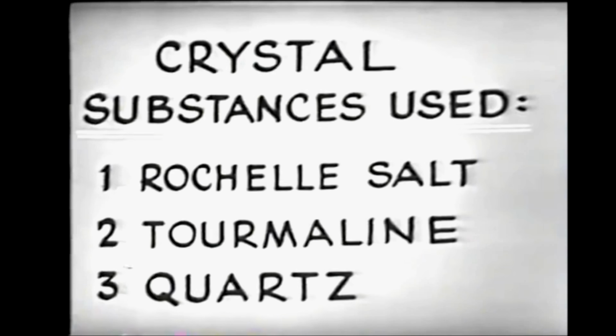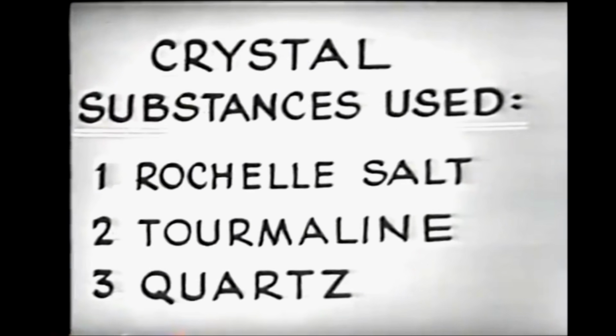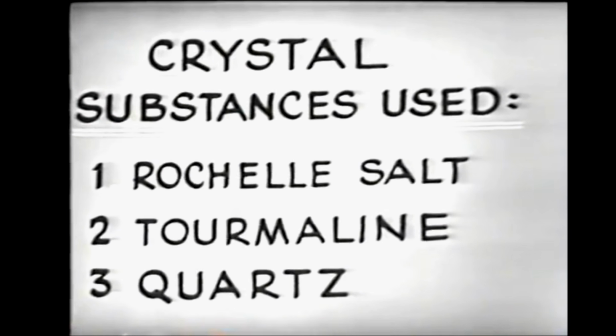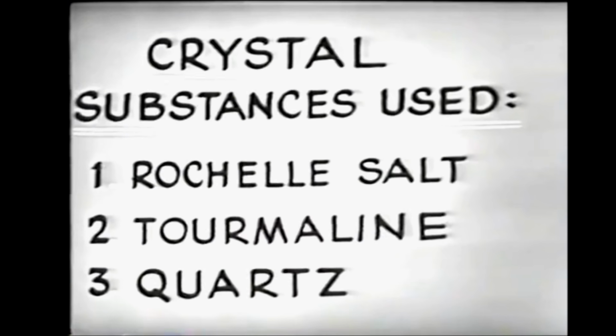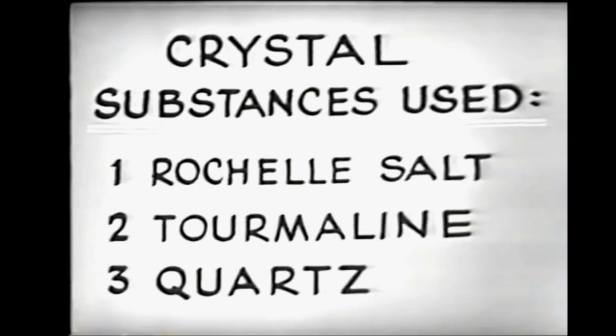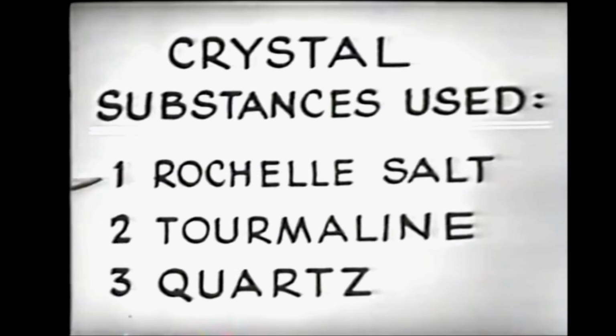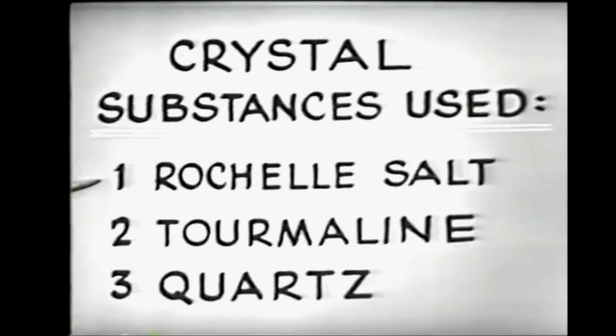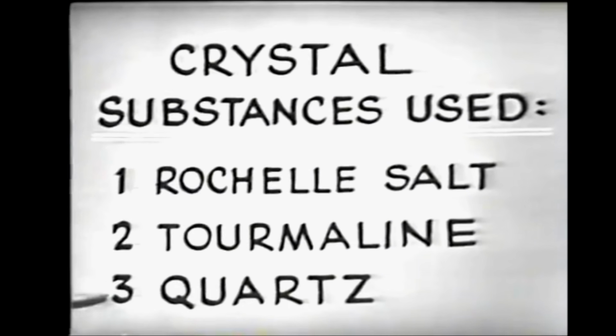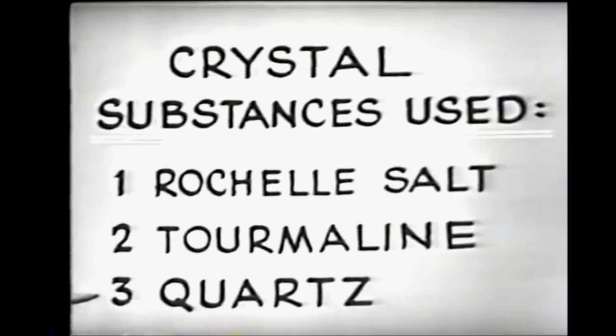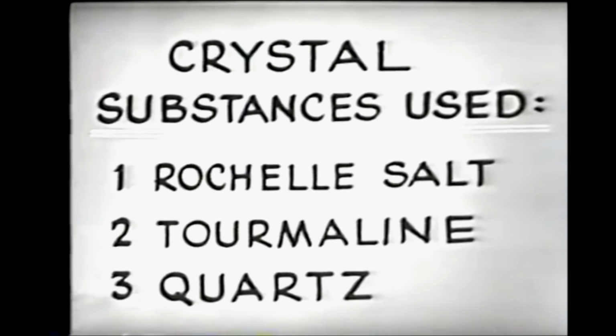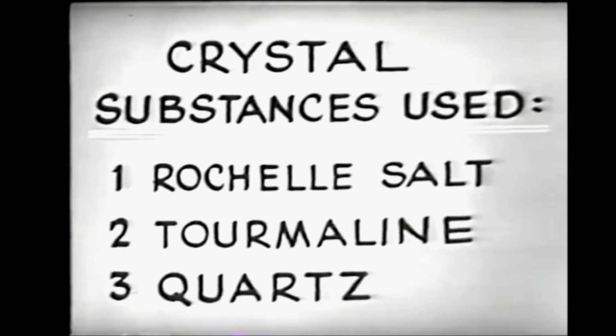Now, let's look at some of the crystal substances that possess the piezoelectric characteristics. They are Rochelle salt, tourmaline, and quartz. Now, of these three, Rochelle salt exhibits the piezoelectric effect to the greatest degree. However, quartz crystal is most generally used because it has a greater mechanical strength. Quartz crystal, remember, has a greater mechanical strength.